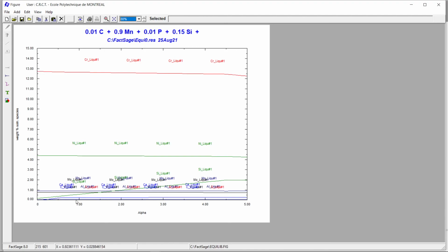However, if we add too much, besides significantly increasing the amount of silicon, we are going to also impact other elements such as chromium and nickel. And decreasing the amount of chromium or even other elements will not be good. So here we conclude the simulations with the deoxidizer agents.